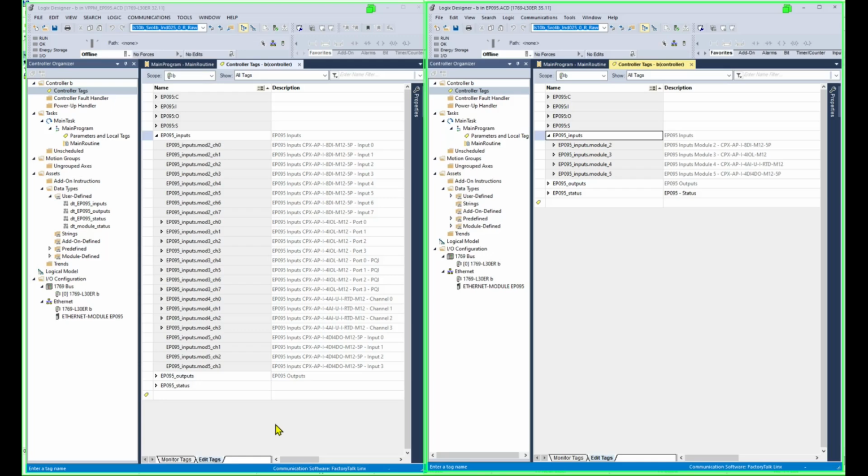This is being shown so that you have an understanding that Festo Automation Suite is a little bit behind with the software L5X export. The web server is more up to date. So the web server has different data type structures, and if you're going to start the project using offline files in Festo Automation Suite, it's important to understand that moving forward, if you're going to start using the web server to do an export, it's going to be a very different structure. So it's important to start on one and finish and continue to use the same platform. Festo Automation Suite will be updated in the future.